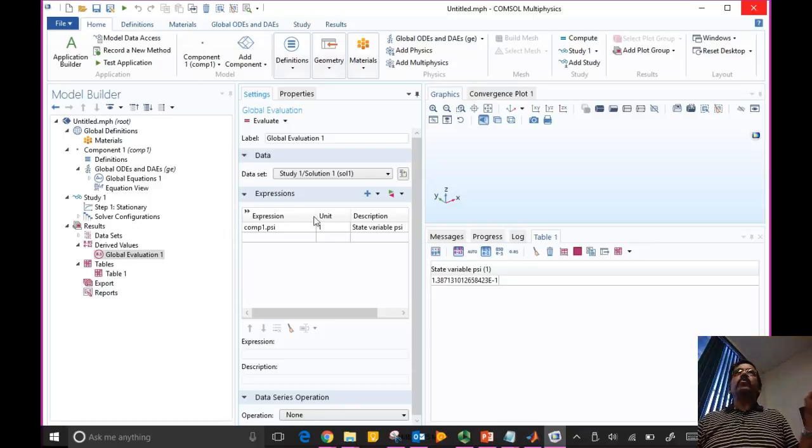Now, the advantage with COMSOL is, if you have a problem like this, and you say, okay, I want to make these k values, which were constants in this particular case, like 3, 1.5, 1, actually functions of temperature. But I have that expression. We can go in there and define those expressions, K as a function of temperature. You can then make temperature one of the unknowns. And you can say, now I want to achieve 50% of the feed going to the vapor. So I give you psi, but you solve for T.